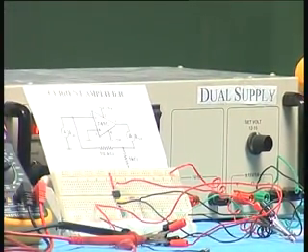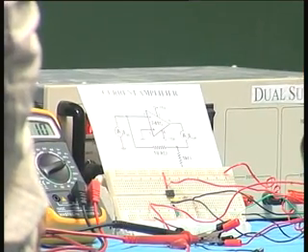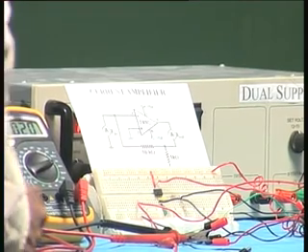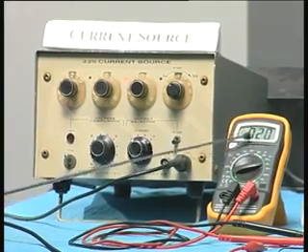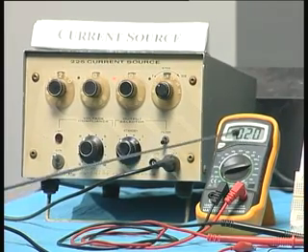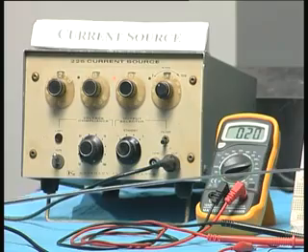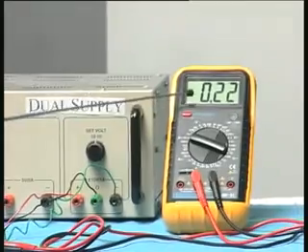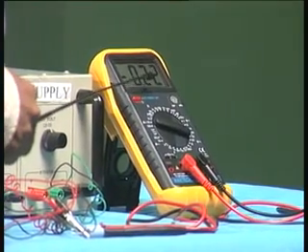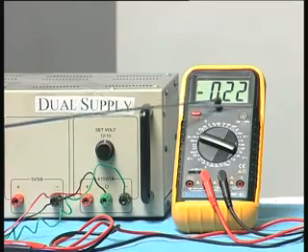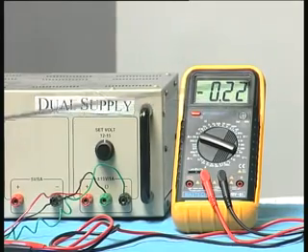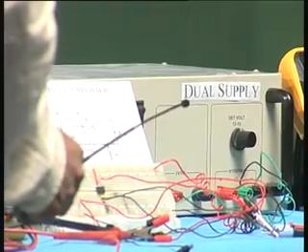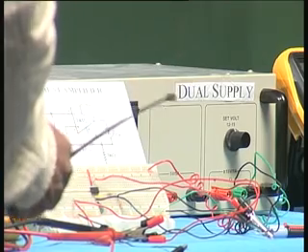Now I am going to change this dial to 20 microamperes, and immediately you can go and see what the input current meter reads. It reads 0.020, which is actually 20 microamperes. Therefore I apply a 20 microampere current. Now I want to see what the output current is. In this multimeter I measure the output current. It shows 0.22 milliampere, which corresponds to 220 microamperes. So 20 multiplied by 11 is 220 microamperes, and that is 0.22 milliamperes.